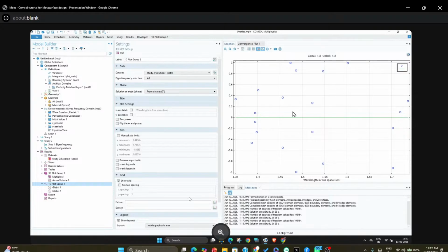But for the degenerate modes, one mode will be Y-polarized and one mode will be X-polarized. Here this comes out wrong, so you cannot identify them. The exact method is that you have to calculate the eigenfrequency from upper excitation and lower excitation, from both sides. That will be later. If you have any confusion, you can ask me in person how we identify the X-polarized and Y-polarized mode. But this is just an example.